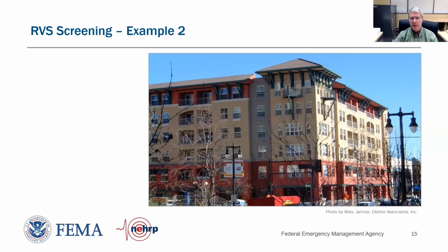So see anything else there that might be some giveaways to identifying our potential building type? Well, I'm just counting the stories. It looks like it's about 6 stories. So let's see, too tall to be a wood frame structure. And I'm trying to think if I would just jump right to that S1, S2 answer that we had for the last example, or whether there'd be other options. Right, for steel.